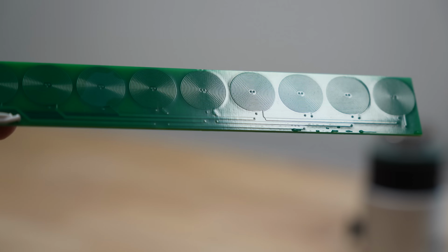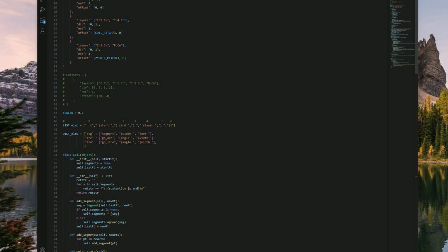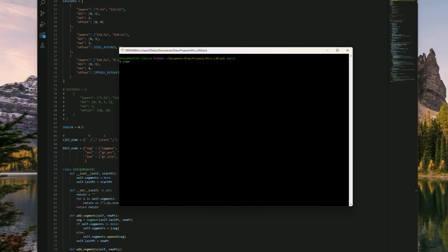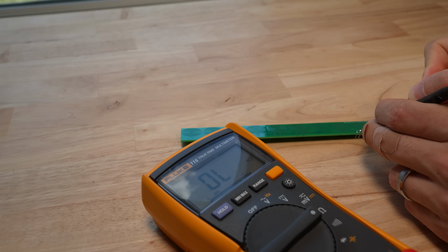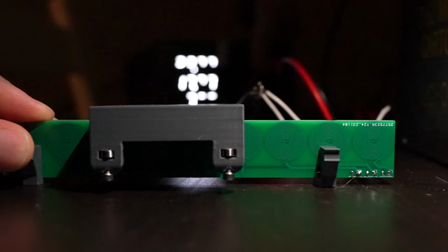These are the first coil boards I generated. I just made them an arbitrary size so I can test some things. Also, I love KiCad, but you can't make curved traces in it. So these are really just a ton of straight segments that I had to create a Python script to generate, so that was kind of fun actually. Now these samples let me do some actual coil resistance testing to see if what I calculated is correct, and more importantly, functional testing. A little bit of soldering later and I had my first hint of performance.